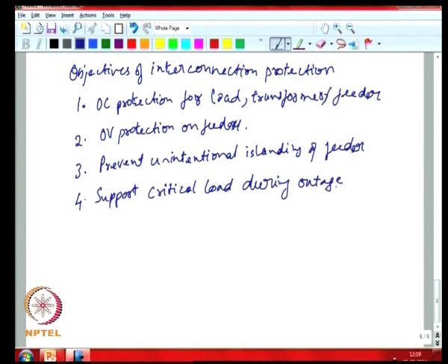The outage is one possibility. You can have other power quality requirements such as voltage amplitude, say sags or swells, frequency, unbalance, potentially harmonics, etc. You want to protect your critical loads from facing poor power quality from the source.